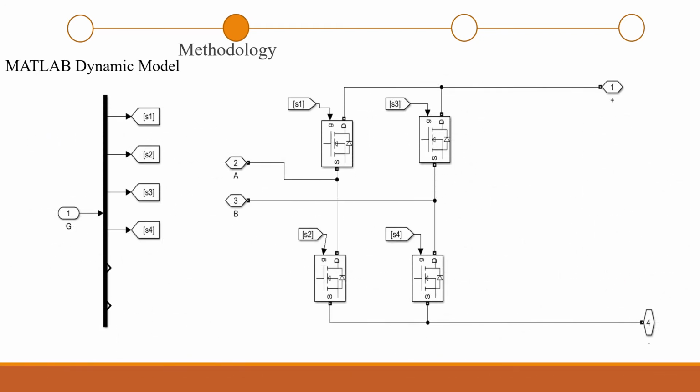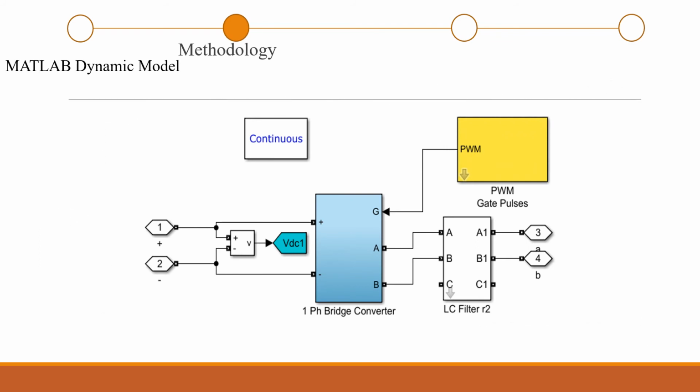The two systems are connected by a one-phase inverter, which has a DC input voltage, and the output is one-phase AC voltage with 60 Hz frequency to meet the Canadian standards. This inverter is PWM controlled, and the voltage is pure without harmonics, as we used an LC passive filter.